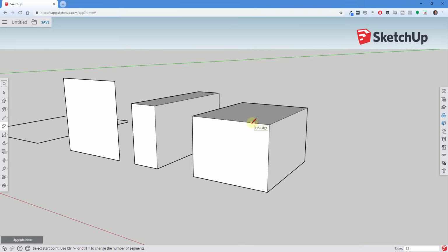And so let's say, for example, that I drew an arc across this edge right here. You can see how what I did is I split this face into 2 different faces. Well, now I could activate the push-pull tool, and remember how before we used this to add material. Well, if I single click on this face and move my mouse to the back, you can see how this actually removes material.